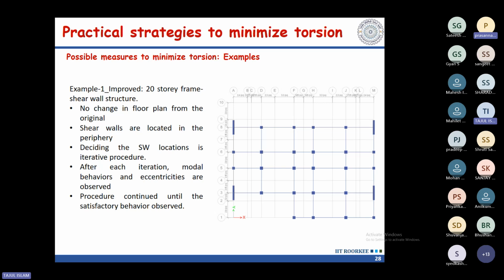No. Spandrel beam, I think it is applicable only when you have the portion above the floor level, door level. So that I think you can model as a spandrel, not the beam. But because they're considering this is also stiff, realistic stiff. Spandrel also same. What is exactly the stiffness that will come into picture? What design criteria do you follow in spandrel? You will divide the spandrel into a number of segments. Suppose 10 meter is there, every 1 meter you will divide it. The spandrel will be assigned a different pier level. The behavior will come as a beam only, but stiffness will improve.